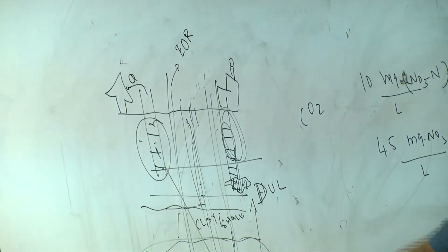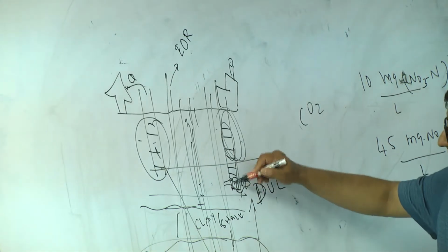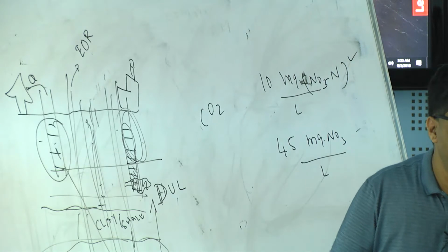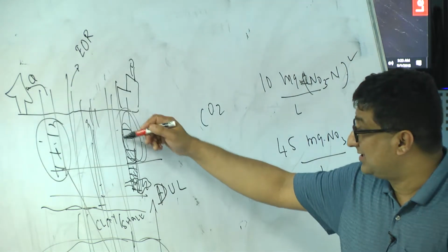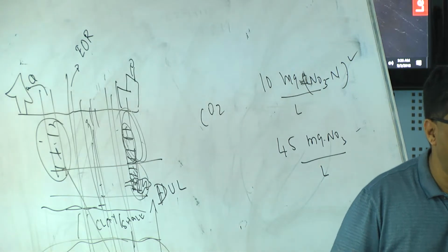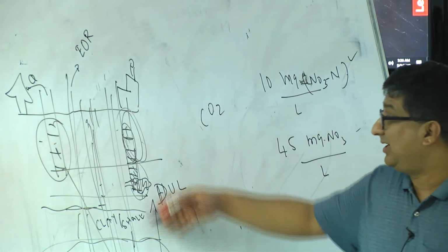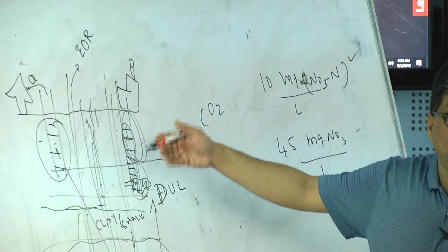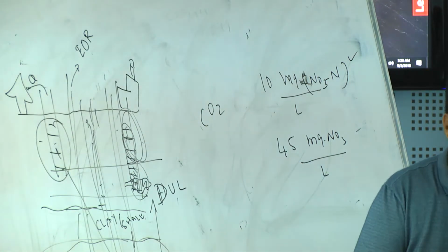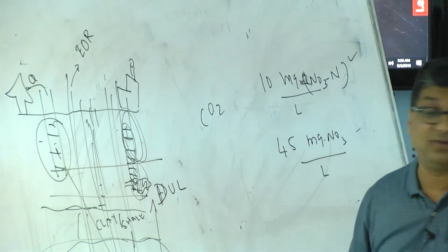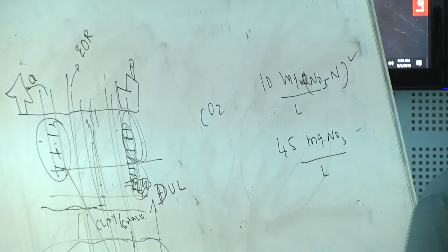Okay. If I had just not screened it here and just had my well till here, I wouldn't have contaminated it. Or on the other hand, if I hadn't screened it here, I would have just had contaminated water from one aquifer, but not from the other aquifer. But by putting a well that cuts across two zones, I've literally contaminated both the aquifers. As a matter of fact, this is illegal. You cannot put a well like this in the state of Texas.